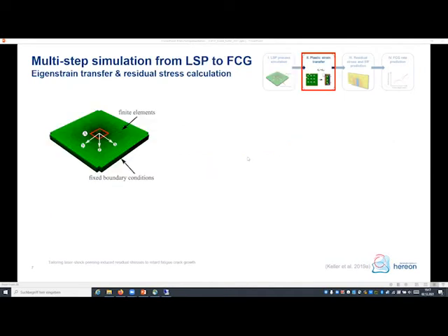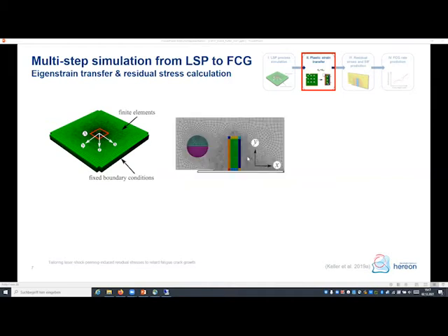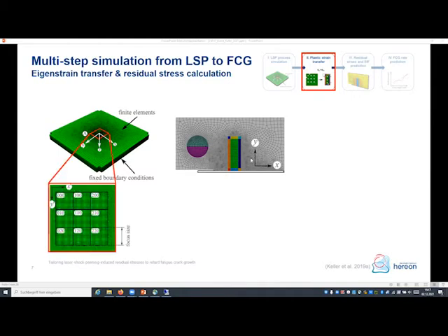So when I have this laser shock peening process simulation, it is able to calculate the residual stresses of certain specimen geometries, and what I'm aiming at are the plastic strains caused by laser shock peening. Then I want to apply these plastic strains to a larger area, as I explained. So the idea is to make use of this periodicity assumption.